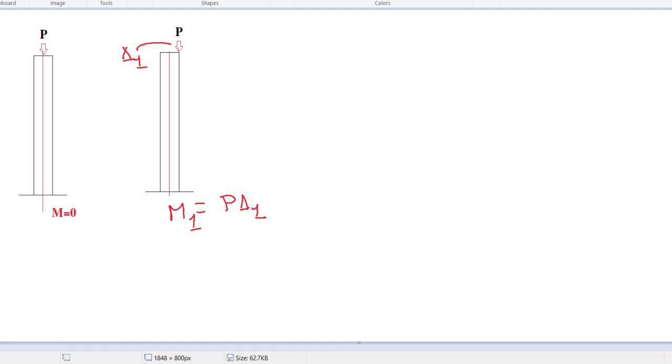That displacement, if I give it a value like delta 1, would be M L square divided by 3EI. So the idea is if you apply some eccentric load, there would be a moment, but also there would be some displacement. The tip would be shifted, right? There is some displacement at the tip by the value of delta 1. Then we can just draw a new shape.